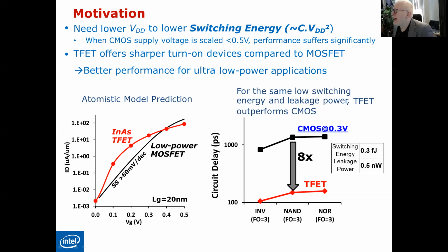But frankly speaking, we are not able to reduce the channel length of the MOSFET using its classical structure. What I mean by classical structure is the structure we deal with in our course: source, drain, gate oxide, and gate. Using such a structure, we are not capable of reducing the overall dimension of our MOSFET.